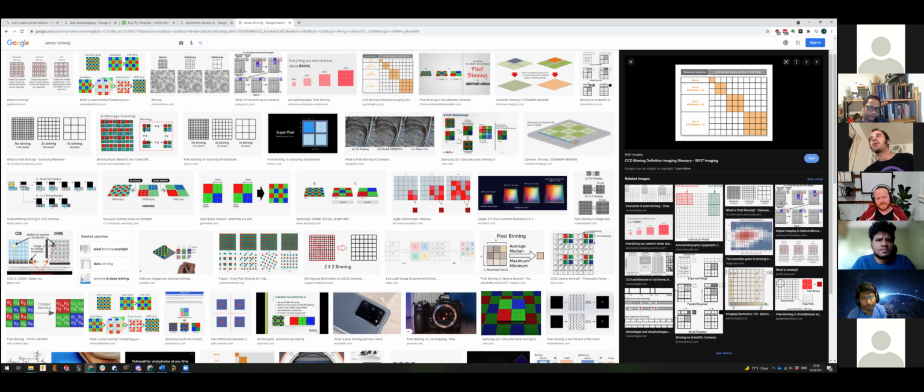This is just where and when we would do it, because there are a few quantities, right? It's frame rate, resolution, and then noise. Those are usually the big quantities that you're juggling with these sensors. And I think you generally assume that your sensor is much faster in terms of time constant than the phenomenon it's measuring. Like a CCD pixel will have a particular drop-off rate of the potential. Any sensor will have that. A good heuristic is you want its bandwidth to be 10x the bandwidth of the phenomenon being measured. And if they come too close, then you get sampling and Nyquist issues going on.